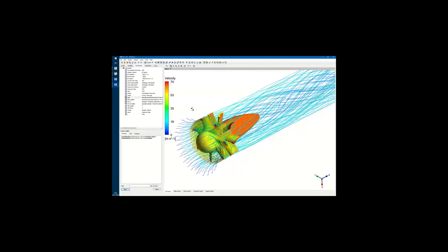What we don't recommend is loss model based performance map estimation. I don't know exactly what the question means, but empirical data, yes, for creating the geometry. However, for getting performance data, we should run 3D CFD. Yep, and that's why the parametric relationship comes in very handy, so that we can explore the design space.